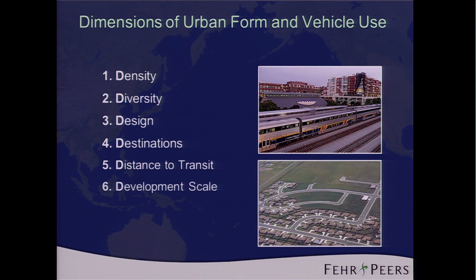The way we understand how scales matter is at the more nuanced level of going into the individual ingredients. And we've been able in transportation and land use interactions to define that in terms of at least 8 critical dimensions. Density, of course, diversity, the mix of land uses, the jobs housing balance, the services balance in total, and also how well integrated they are within the urban environment. Urban design, the network density, the interconnectivity of the transportation networks is important. Destination accessibility, critical, and we can measure these, and I'll talk a little bit about those.